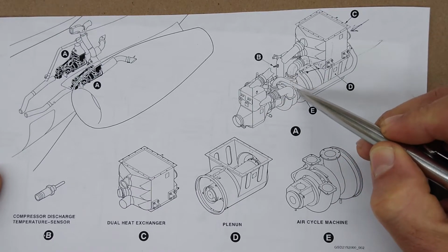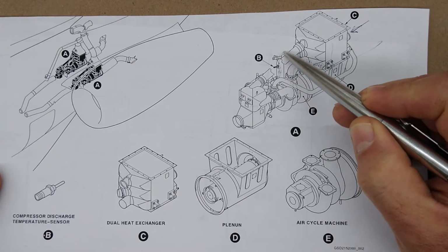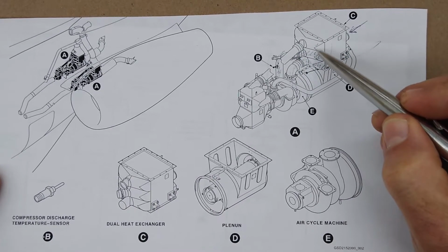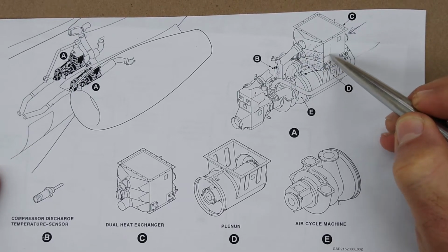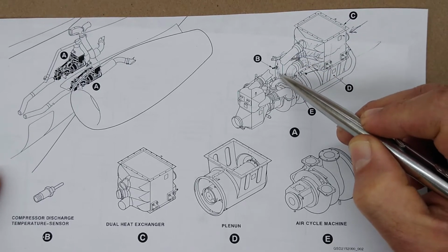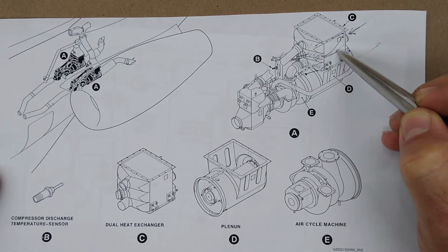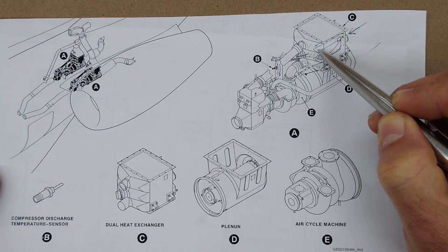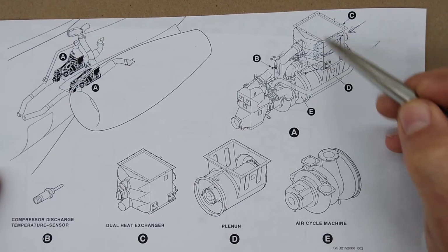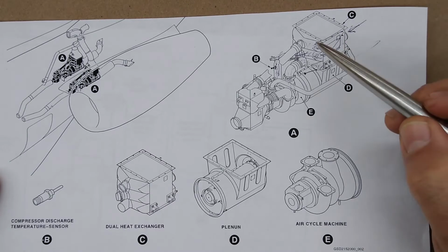Here's the inlet to the compressor where it gets compressed, and it gets piped through here back to the main heat exchanger, which is these two. It goes in through here, up and out, back through here. So again, this is the compressor outlet, comes into here, into that heat exchanger, up here and back out through here. So it goes through two floors of heat exchanging here, again being cooled off by ram air flowing through here and taking all that heat out and dumping it overboard out the back of the airplane.